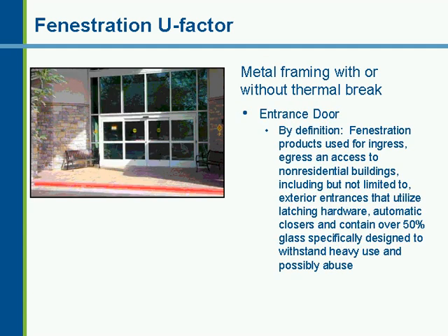Entrance doors are another category within the IECC. From an entrance door standpoint, by definition, this is fenestration products used for ingress, egress, or access to non-residential buildings, including but not limited to exterior entrances that utilize latching hardware and automatic closers and contain over 50% glass, specifically designed to withstand heavy use and possible abuse. So the example shown in the left-hand column would be considered an entrance door.